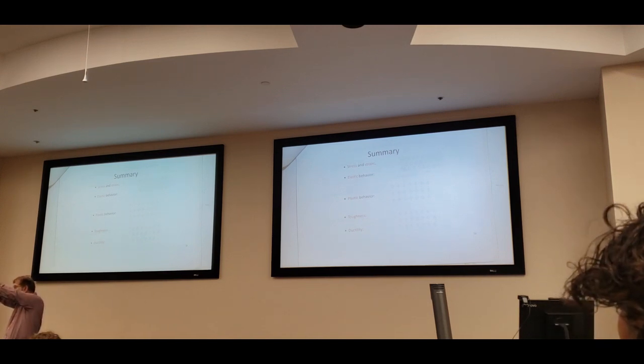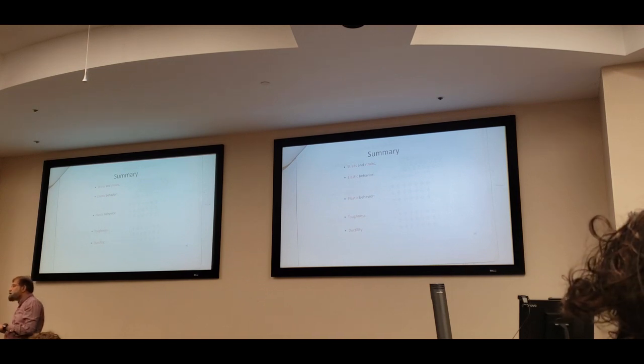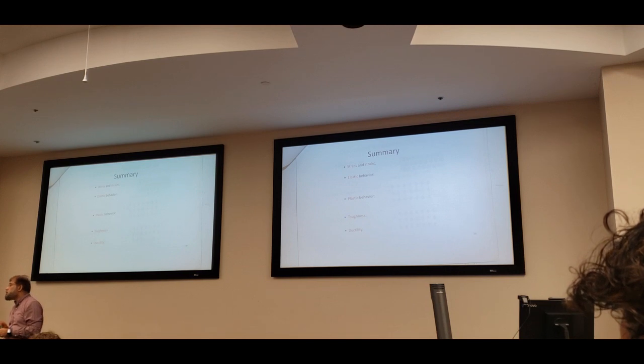If you try to bend it like this one, what happens to a ceramic? Think about a very, very thin ceramic plate. It breaks right away. Right? So there is very little plastic deformation in that case. Whereas you have a polymer, for example, this one. If you try to bend it, what happens? It is still bent, right? That is the plastic deformation.